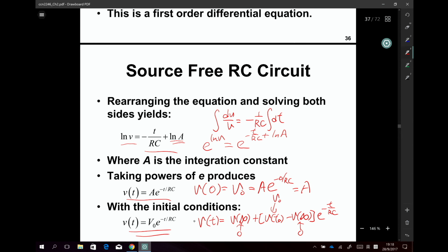So immediately it gives you this formula. Right? I told you before that the general solution is very important because you can substitute the initial condition, final condition, and the time constant into the general solution. You can get all kinds of solutions in the first order circuit. Okay. Now, any question here?